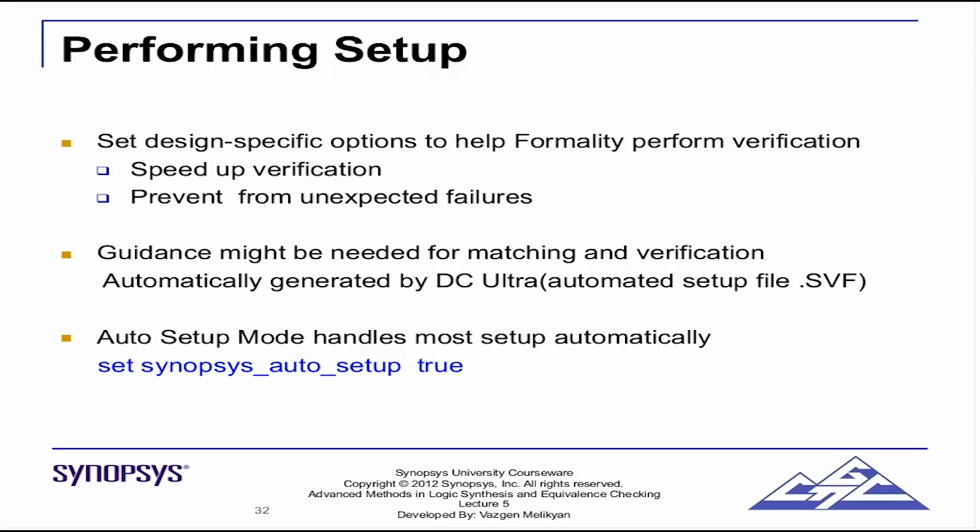So you will have to spend some time in setup to make sure that the verification goes on fine. And this is an iterative process. It might happen that you did not initialize or did not set the correct value of some variable, and you find a lot of compare failures. Then you find, okay, I missed setting this value. So you go back to the setup part, set the particular variable, and then go and verify again.